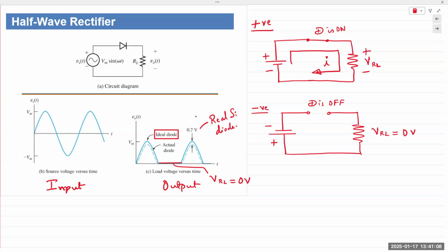Now, a typical question would be: how in the world is this a DC rectifier circuit? Isn't it still AC? And the answer is yes. Without any additional filtering elements, we can call this an AC waveform, or I like to call it a pseudo DC waveform. It's still in the positive direction, it's not going negative, but essentially it is still a time varying voltage. So we can treat it both as an AC as well as a DC waveform. It's not a flat line.